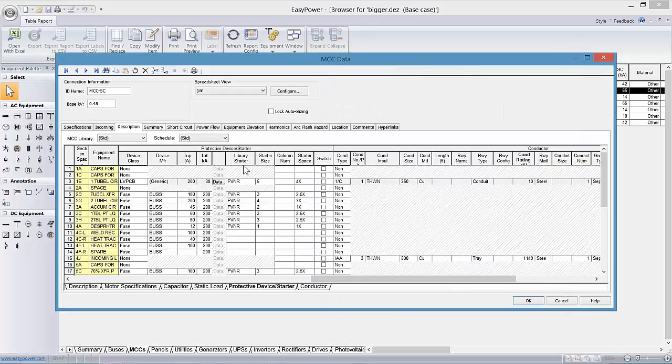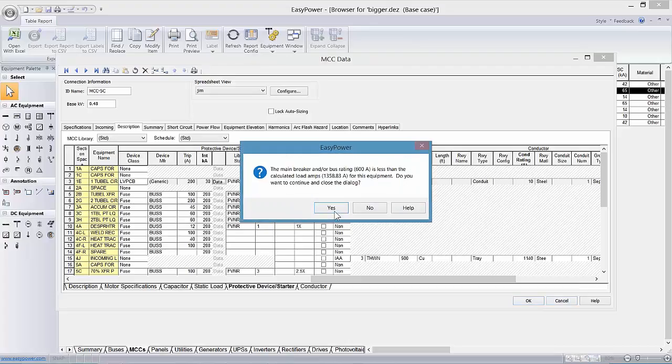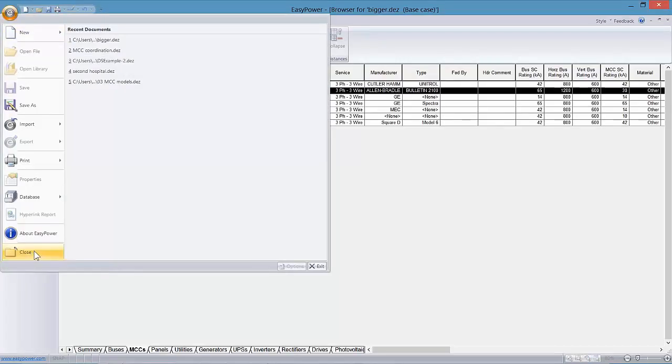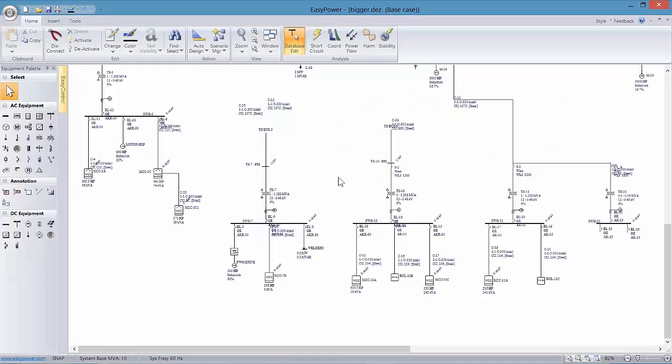So all that's involved. In fact, that's primarily what's involved in setting up the TCC to utilize the TCC in the motor control center. Okay, the benefit then is, rather than just have the 50 buses that we're dealing with, we have quite literally over 200 buses now, or 200 loads that are included in this design, and we haven't used anything more than a 50 bus limit on the whole system. Consequently, the tool requirement's smaller. Okay, so that's what I wanted to cover there.